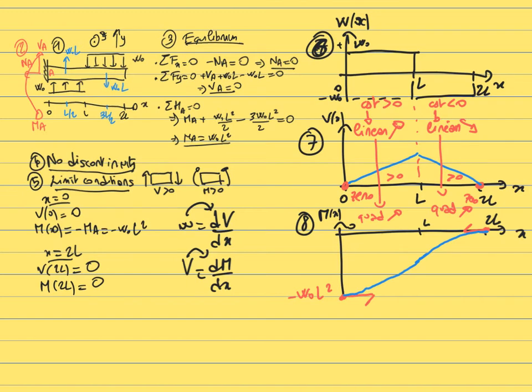So this is a convenient tool to quickly see at which point the internal shear and the internal moment are going to be maximum, which tells us where the stress is going to be maximum, which in turn tells us where the beam is the most likely to break. Again, if your goal is not just to get a graphical trend for the internal shear and the internal moment, then you will need to numerically calculate the internal shear and internal moment.